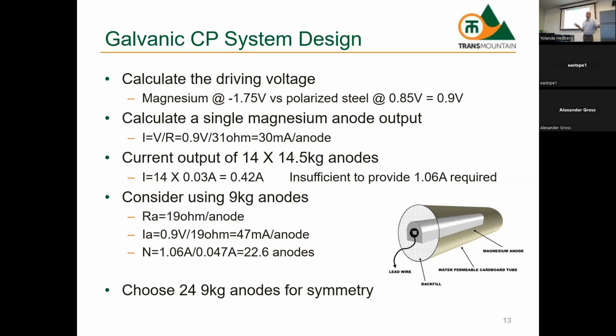Isn't there something conductive like coal or carbon? That's in impressed current systems. Impressed current systems use petroleum coke breeze or calcined coke, which is carbon powder, for that backfill. Because there you want the carbon to actually consume before the anode, so you extend the life of the anode.